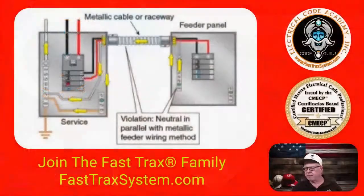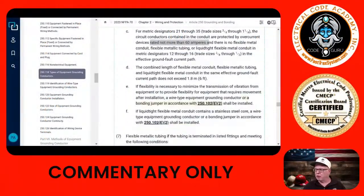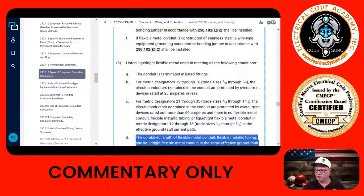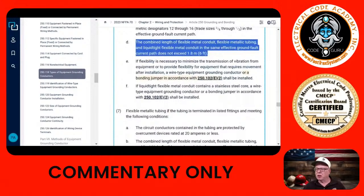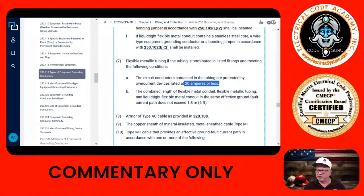All right, so let's go back to the code here. So anyway, there you go. And of course, there are length limitations as well that you have to be aware of when it comes to liquidtight flexible metal conduit. Now, what about flexible metal tubing? All right, well, can't really say that we can use this because, again, that's limited to conductors that are protected by a 20 amps or less overcurrent device, so that's not going to really play a role in our example.